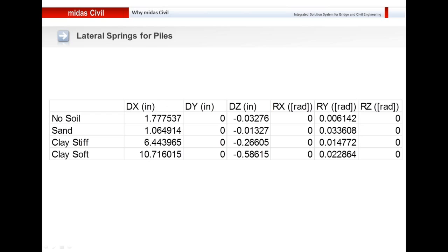The deformations for the Z direction would be more or less the same, but when it comes to lateral direction, like global X or Y direction, in which, when the earthquake hits the bridges, it always deforms majorly in the X and the Y direction. And as you can see here, modeling the soil can make a difference.